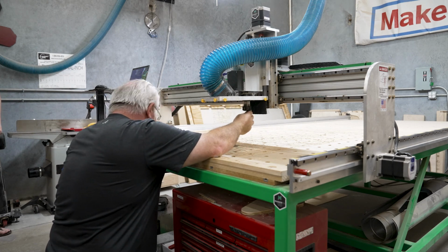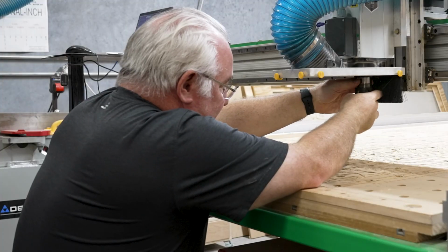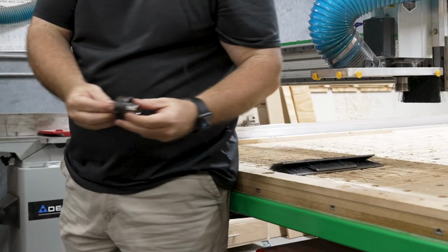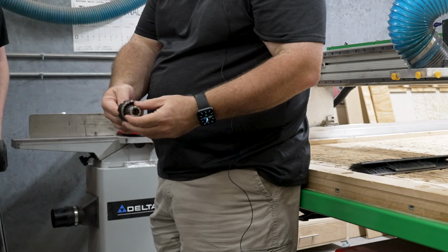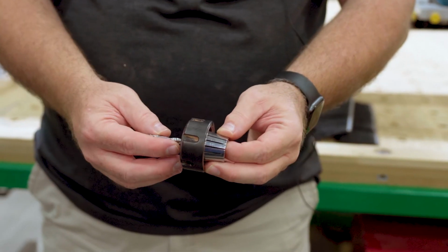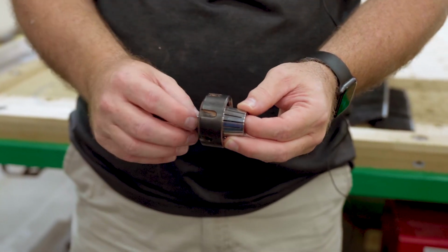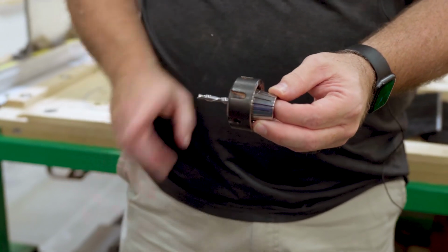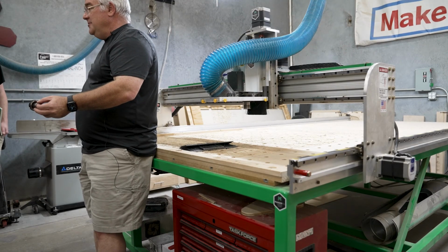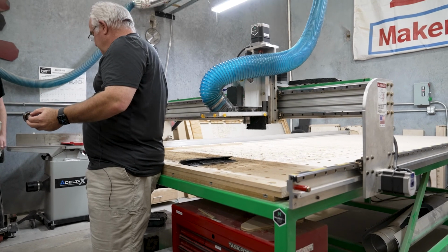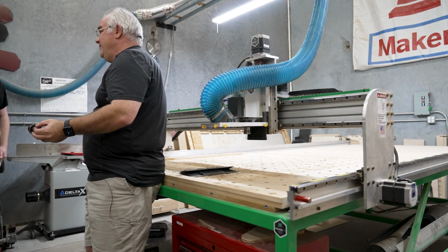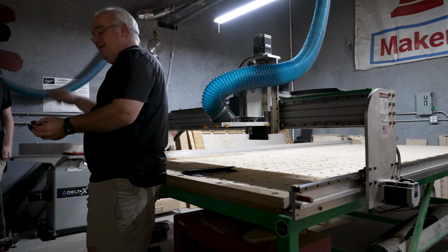Now, people ask, how far out of the collet does the bit need to be? I'm going to go ahead and take this nut off and do this again. So you should not push it all the way up, right? That's not correct. At a minimum, you want to have your cutting edges out. So that would be kind of a normal position. But you also want to think about the job that you're going to run. I can speak for this firsthand. These dog holes, there are 2 pieces of 3/4 inch plywood, or MDF. I needed to go all the way through them, an inch and a half. I created a job and told it I wanted to go through an inch and a half.